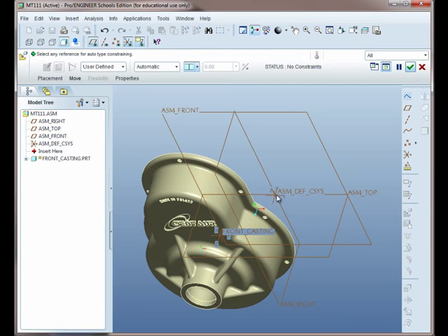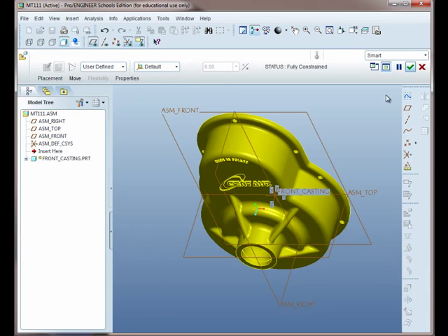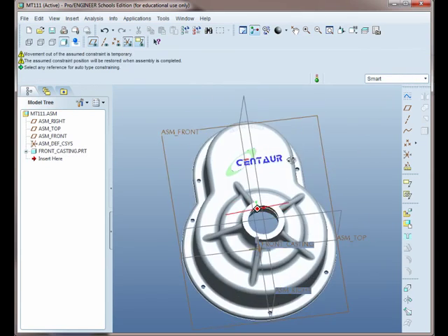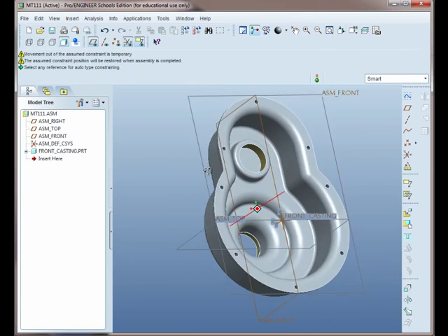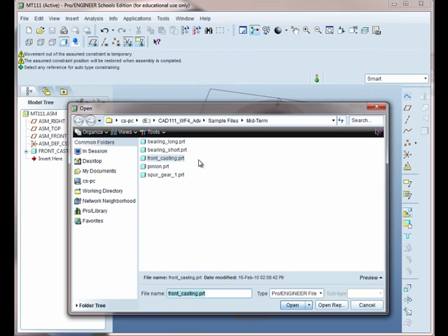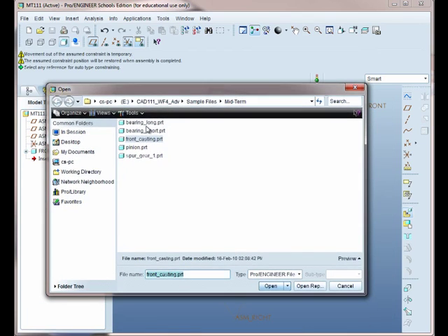And what I want to do is lock it onto the assembly origin. So instead of automatic here, I could go with default, and then I just hit apply. Now I'm going to go ahead and add a few of the other parts. So I could go over here to Assemble again, and I'm going to drop in the pinion. Actually, we'll drop in the bearings. There's long and short bearings. We'll go ahead and add, in this case we need a short bearing, just one.